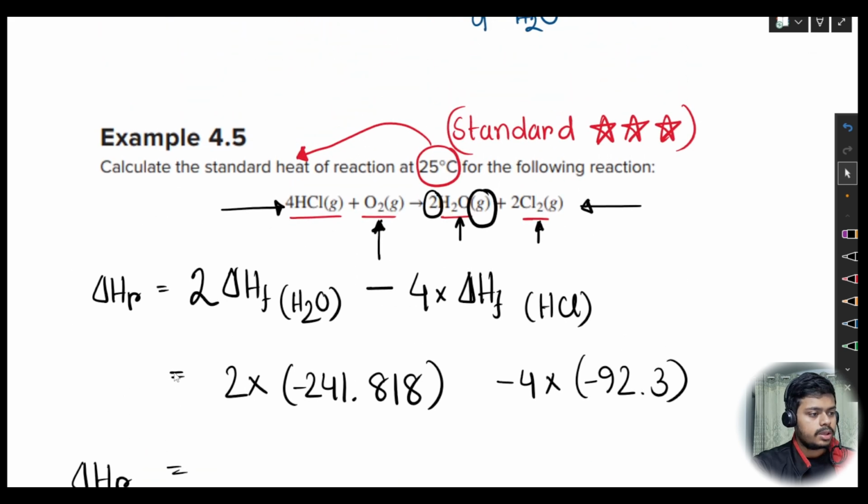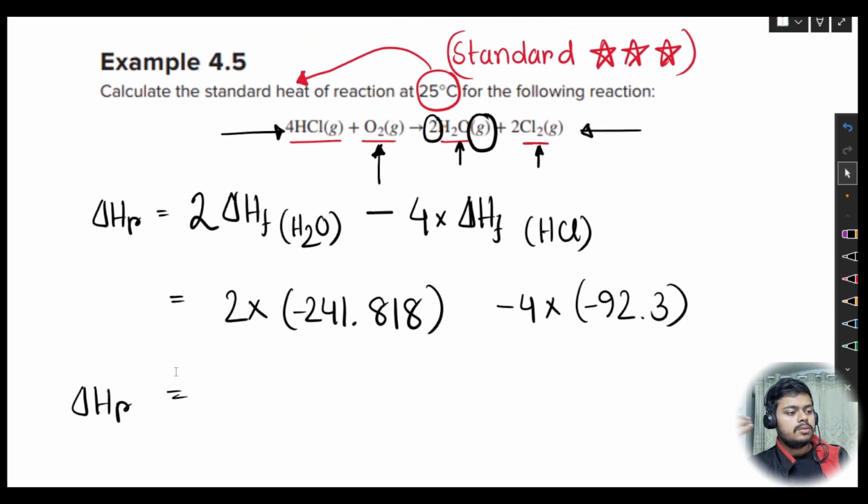Okay, so I think we are pretty equipped with knowledge about calculating the heat of reaction in the standard condition, right? For the standard condition, we just simply determine the heat of reaction equation through the values of heat of formation. Look up the values from the book of Smith in table C1 to C4. Basically in table C4, the heat of formation values are given. So include those values in the equation, and then bam, you get your heat of reaction value.